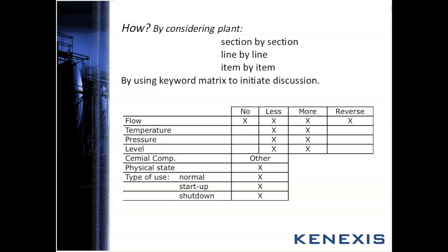For each credible deviation from the normal process control, a credible cause and a potential consequence of that deviation is reported. So a fundamental assumption is when a process is operating in its design envelope, the potential for the hazard and operability problem does not exist. So as we can see, the process safety information is very critical for making sure that you understand your process and the parameters that you are HAZOPing against, okay?